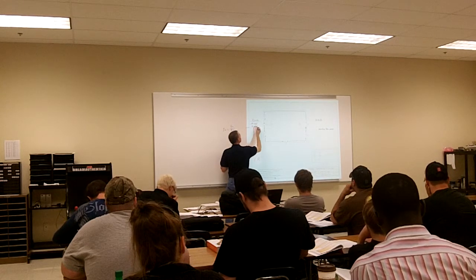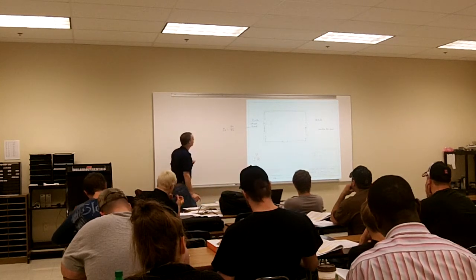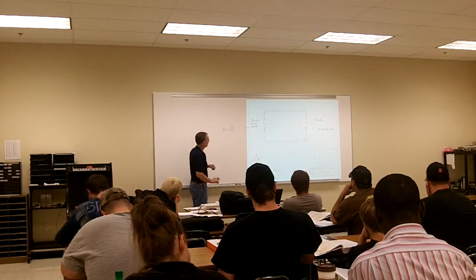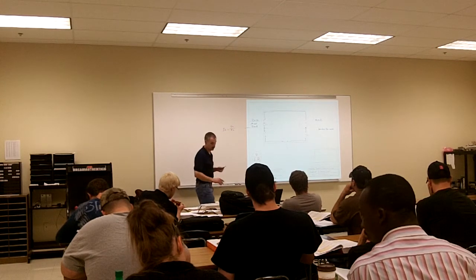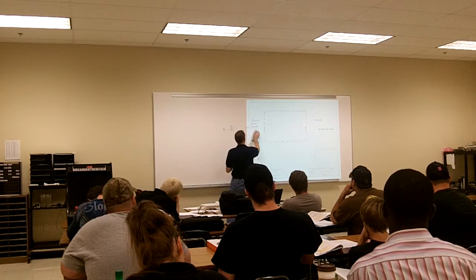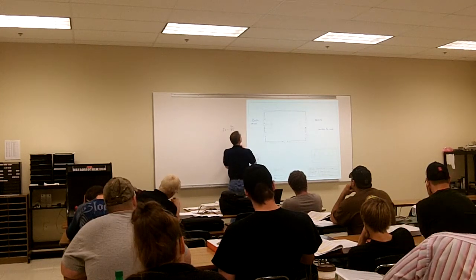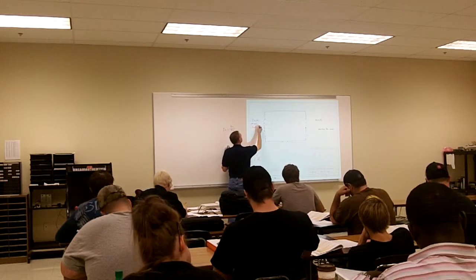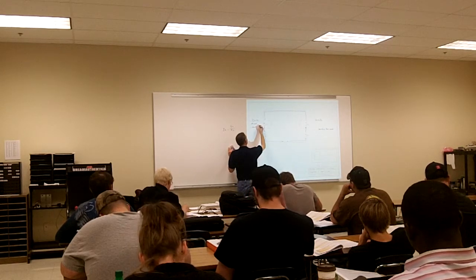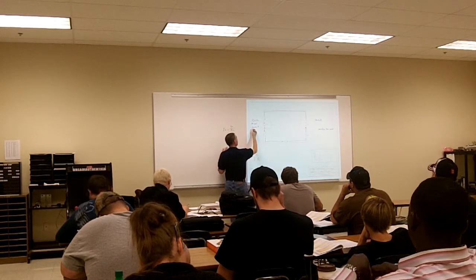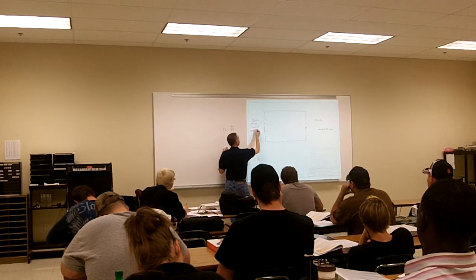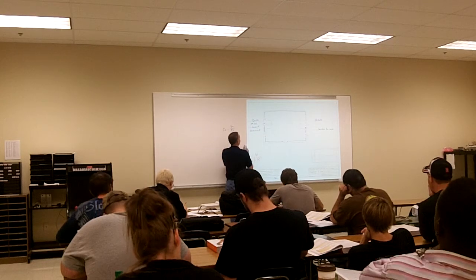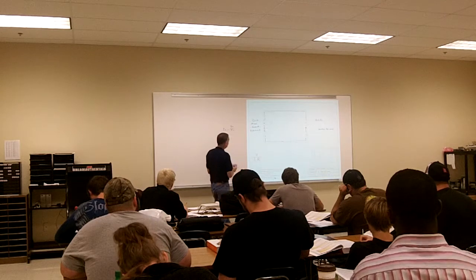You said volts divided by my resistance. So you're saying 24 divided by 120? Yep, 24 divided by 120. That's a 0.2. What did you get? 0.2. Is that in the proper metric prefix? No, so that's the wrong answer, right? You have to make sure you get your four digits because that was a calculated number. So what your answer should have been would be 200 milliamps.